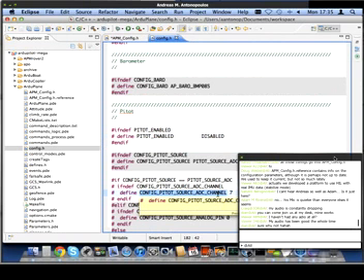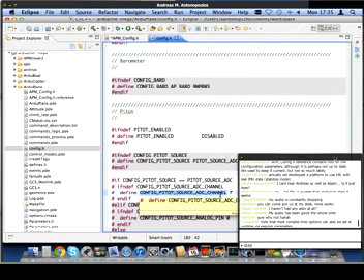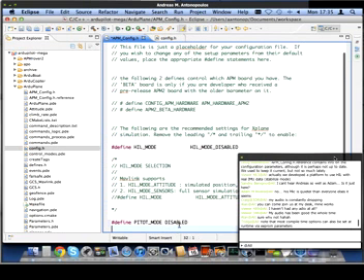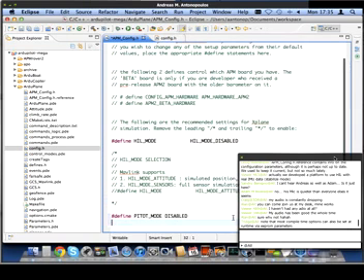So I basically look into config.h, I see something, and for example here the pitot is on channel 7, and I want to change that. I can go and define that and change it to channel 8 or channel whatever.